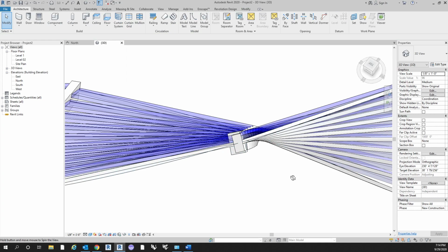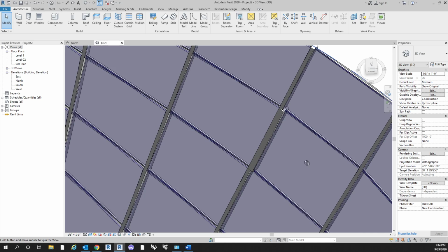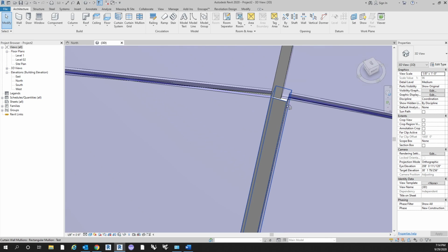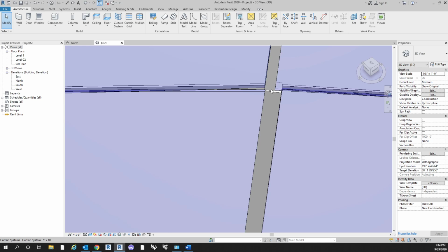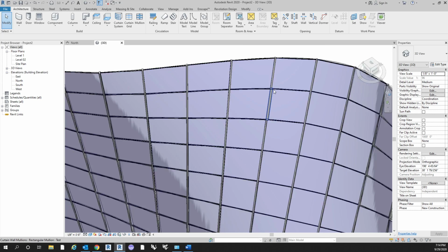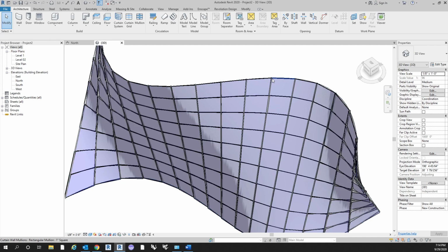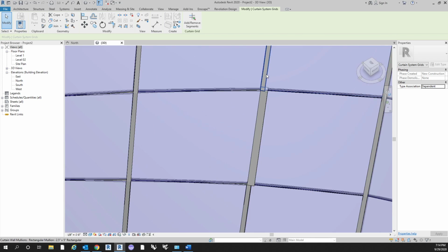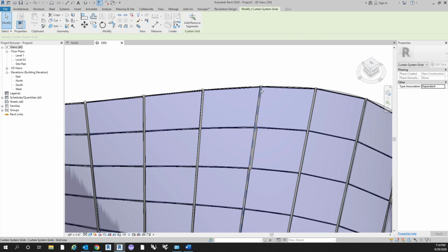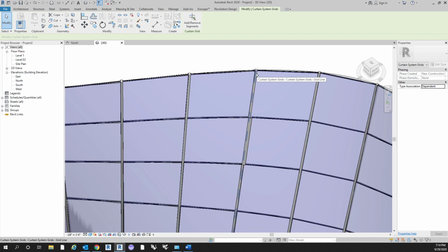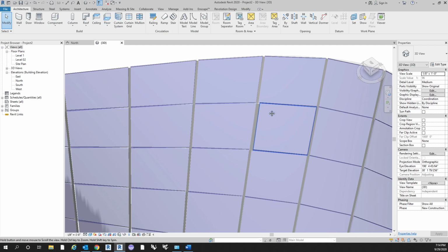center of the face. And then the 1 inch on side 1, as you can see, if I can tab in and grab that. Here, let me see, so I can visualize this for you guys a little bit better. That dashed line, oh, there it is. That dashed line that you see, that's the grid. And so the mullion, we created a thickness of 1 inch on one of the sides of the grid line and then 3 inches on the other. So that's why it's asymmetrical off the grid.